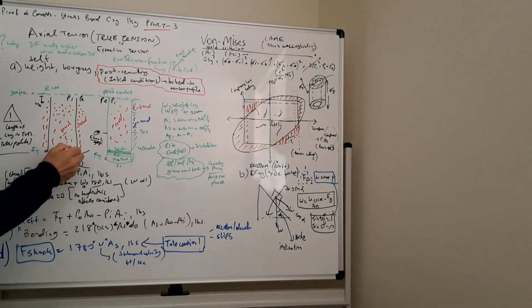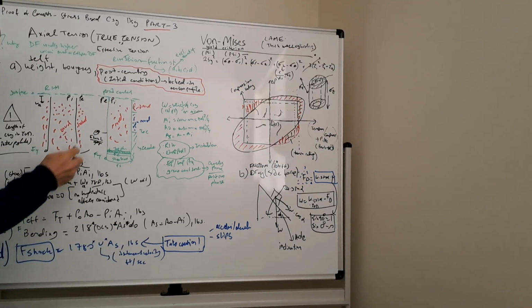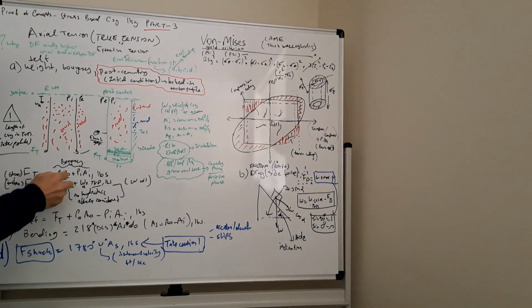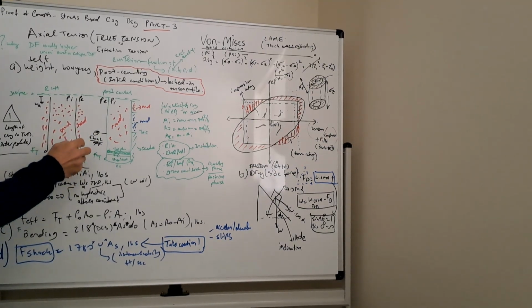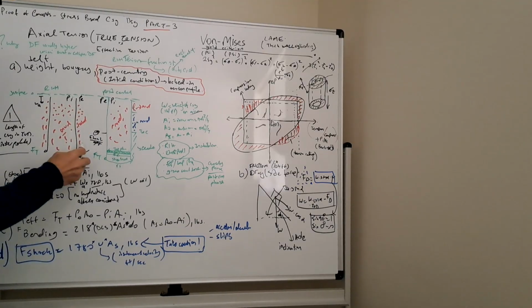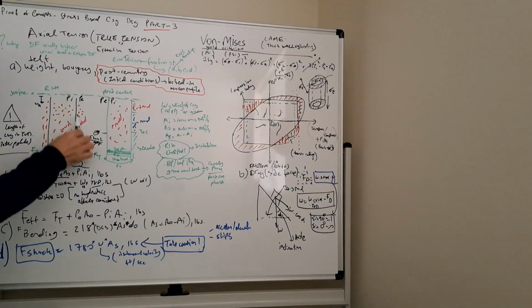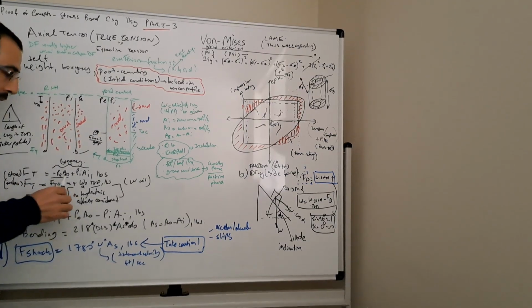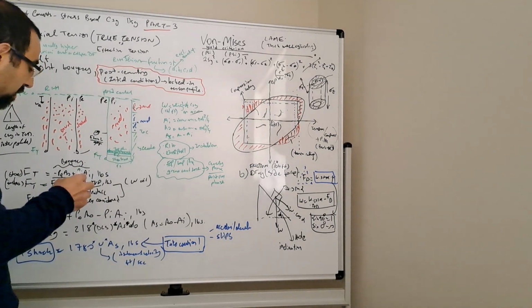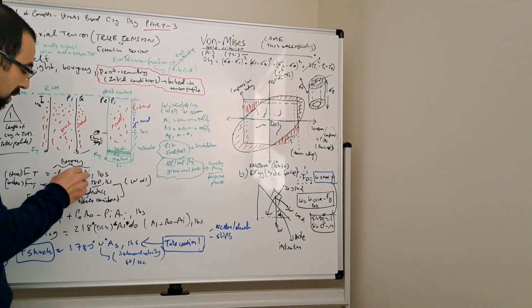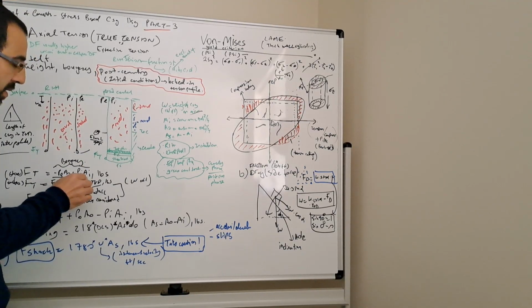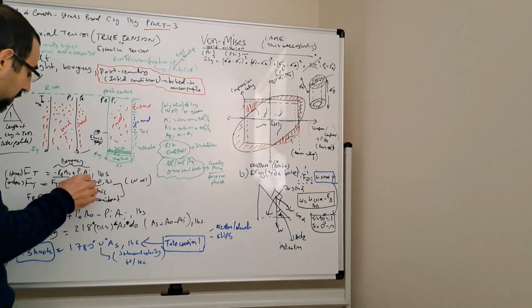So the true tension at the shoe is basically the minus of your external pressure times the external area. That's the force that's applied on the shoe on the outside. That's hydrostatic, and for this hydrostatic, you remember, you will use the TVD of the corresponding MD if it's a deviated well, and on the plus side you will have the internal pressure times the internal area.